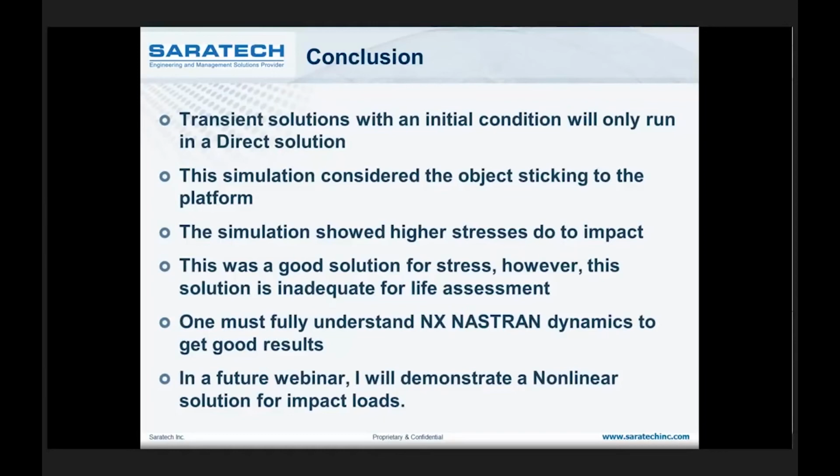This was a good solution for stress, because if the question was, did it break, did it bend? It gave you the answer, yes, you bent the structure. However, this solution is inadequate for life assessment. And for life assessment, you need cycle counts. If I used this solution for life, you need to continue on through the sim as the thing is potentially breaking contact with the surface, and you can't do an adequate cycle count with this. You'll have to go to nonlinear.